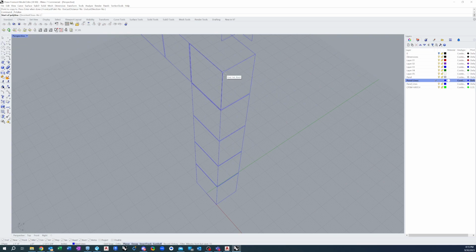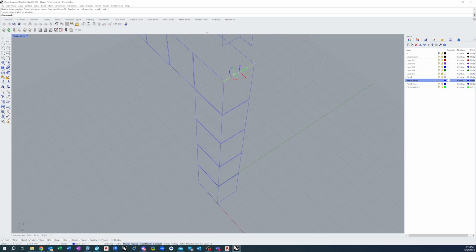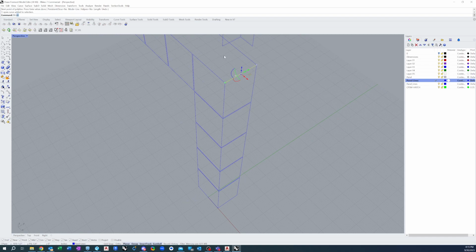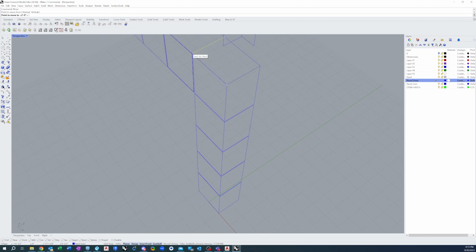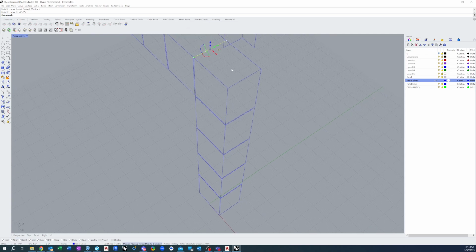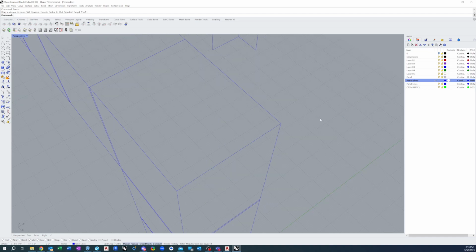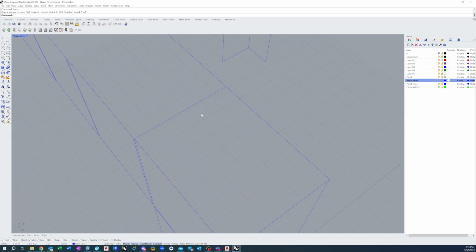Alright, grab this guy and draw a line over it so I can copy it. I'm going to move it. So since we're in 3D, and you click a line, there might be another line behind it, so it always asks you which one you want to grab. So obviously grab the curve, MO for move, move that to here. I'm going to do my zoom to get my view reset. I don't know why it does that, but